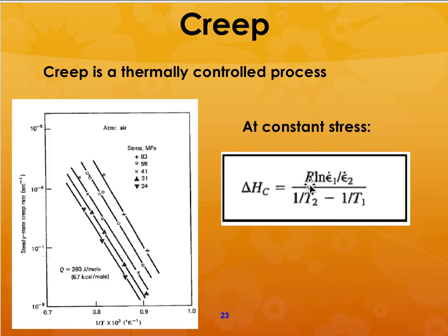From that you can calculate, for the same stress level, the enthalpy required for the creep process. From that you can calculate what is the lifetime, or what is your creep rate, for your particular component. So if you know the creep rates and the temperatures, you can actually calculate the enthalpy at a constant stress.